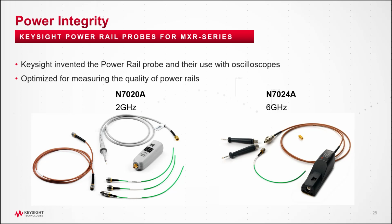Now you see the 2 models that we've got. We've got a 2 gigahertz and a 6 gigahertz. And those may impress you as being high bandwidth, but it isn't uncommon for there to be localized high-frequency noise in the PDN that can actually end up radiating and polluting the radios in your wireless device. So sometimes you actually need that extreme bandwidth for chasing down your PI problems.